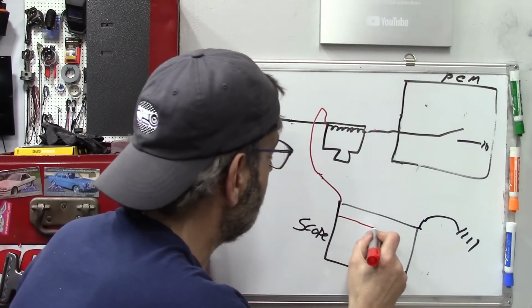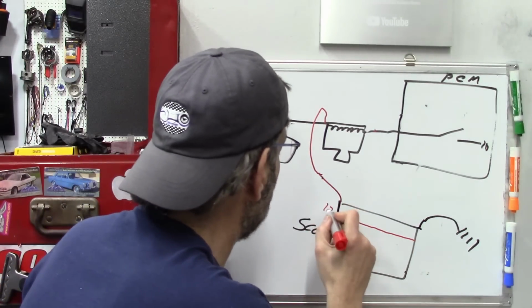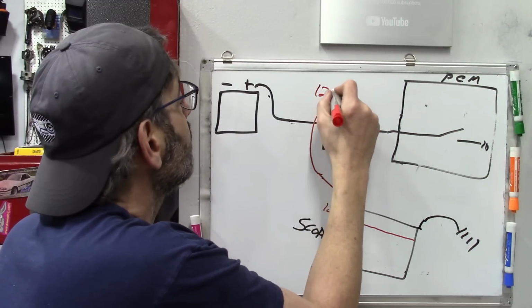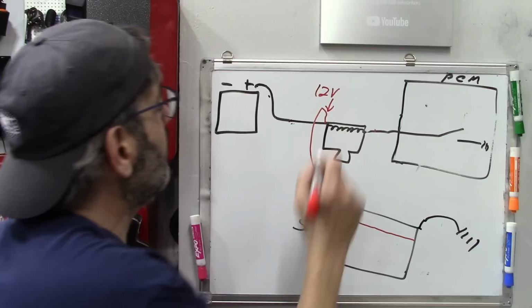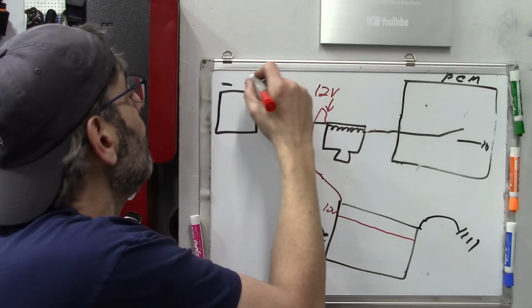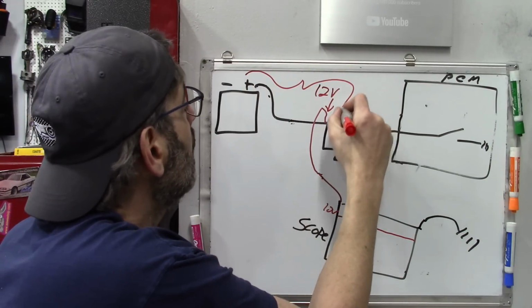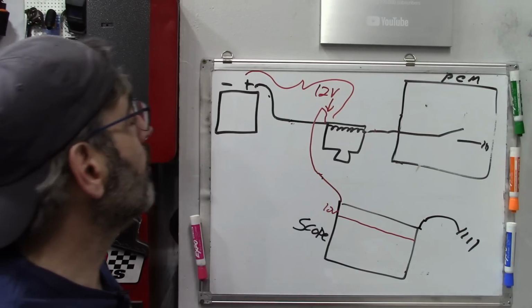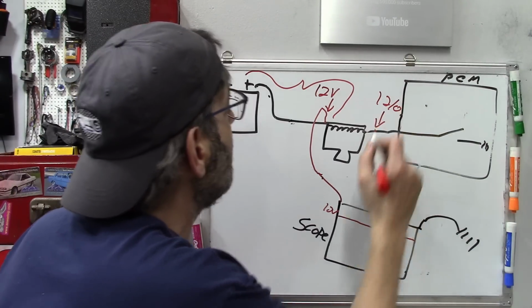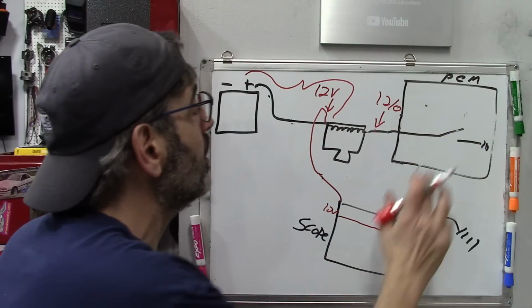It's just going to give a straight line at 12 volts. Why is that? Because of what we talked about all through this video. It's always 12 volts here. It's 12 volts anywhere along this part of our circuit. The only change with 12 and 0 is on this side as the switch opens and closes.